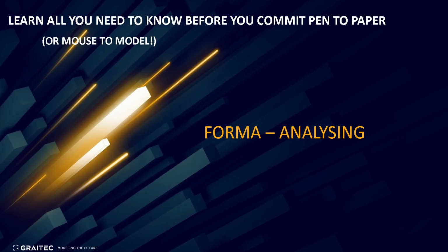We're going to start with our analysis tools. Now, some of these analyses do take time. Some of them take up to 40 minutes, somewhere around there, for some very detailed analysis. But before I do the analysis, if I'm going to do noise, is the one I'm thinking of at this stage, you're going to need to set up your roads and rail with noise or average annual daily traffic, average daily traffic.